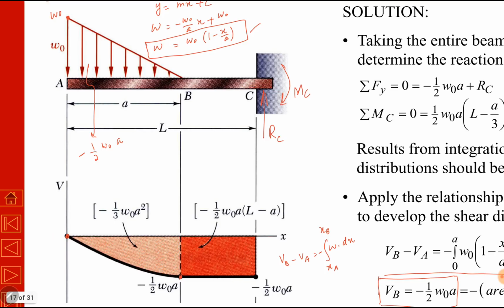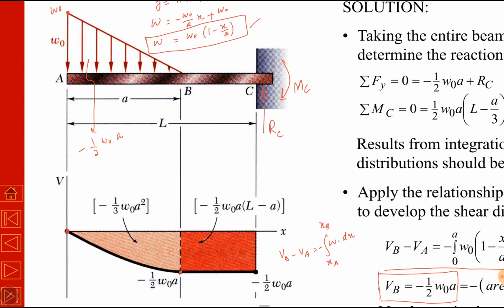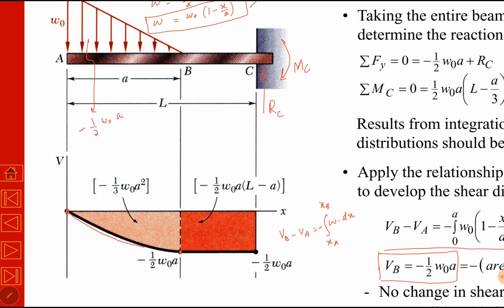Now there is another convention. Previously we explained the relationship between bending moment and shear force. If the shear force diagram between 2 points has a decreasing slope, the bending moment curve will be clockwise. Here it is opposite. If the slope of the load curve between 2 points is decreasing, just like between point A and B, the shear force curve will be counterclockwise. So here it is, counterclockwise. Then from B to C, there is no distributed force between B and C. So the shear force will remain constant.